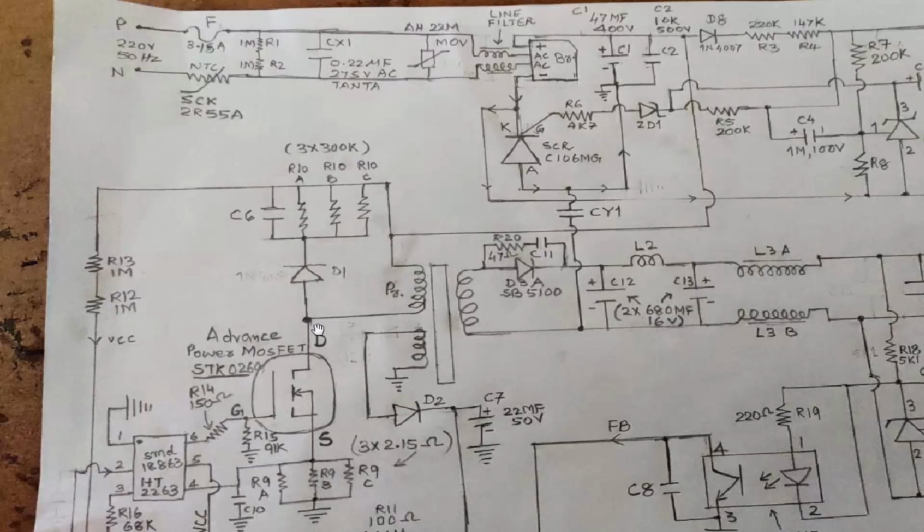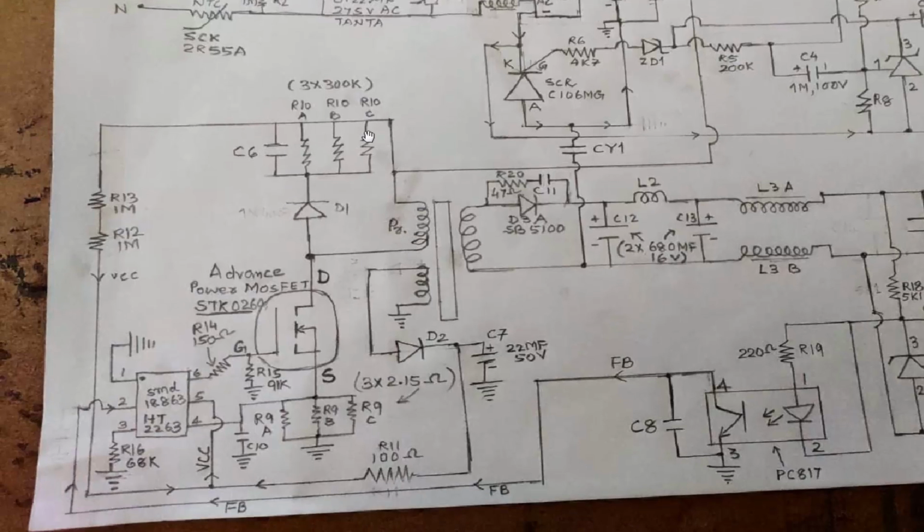positive voltage has only one way to discharge. So this voltage will discharge through this path, because it has only one path, since the MOSFET is in the off condition. So only the positive voltage will complete its path in this way. Current in the primary will be zeroed and stress on the MOSFET will decrease, so that it will get ready for the next switching.